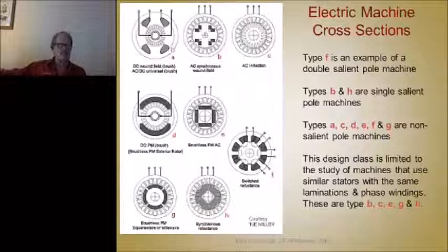Here's your field windings in the stator, and then your armature windings on the rotor. And those are the commutator bars there, and these represent the brushes. So each one of these coils is here's one pole, there's the second pole. So that means that the coils are going to be wound across 180 degrees apart. There'll be a coil there and a coil there, and then pairs of those coils wrapped, stepped all the way around in a lapped fashion.